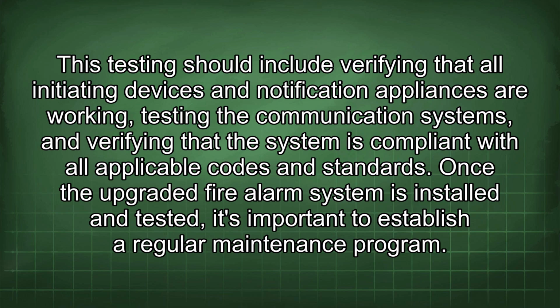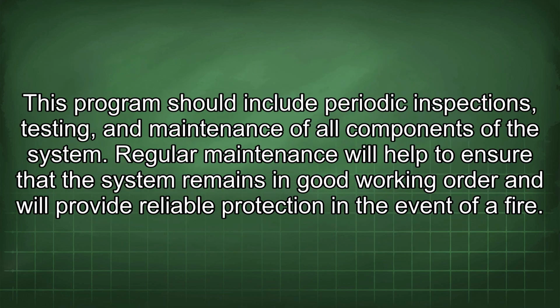Once the upgraded fire alarm system is installed and tested, it's important to establish a regular maintenance program. This program should include periodic inspections, testing, and maintenance of all components of the system. Regular maintenance will help to ensure that the system remains in good working order and will provide reliable protection in the event of a fire.